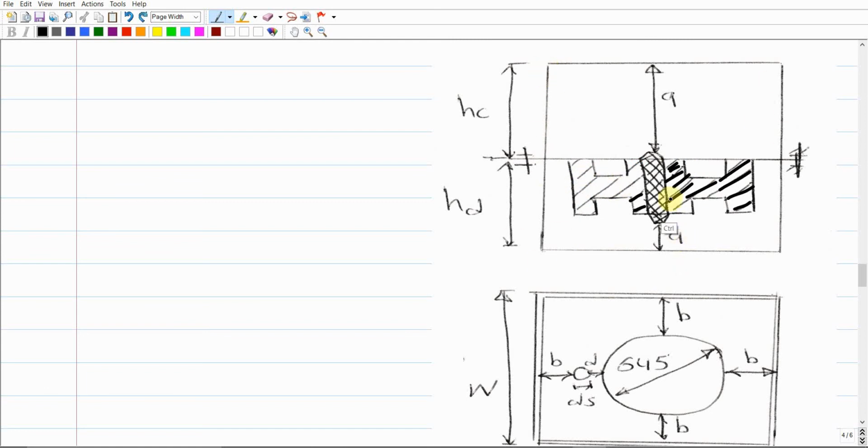as we agreed before, right? And as you can see, there is a standing vertically the core itself. This should be the thing in the middle, this should be the core, and these extra portions here are the core prints, right? And from our calculation, we find that this dimension is the H1 that we got from the table in the core design step by 70 millimeter, and the one on the top was the 0.6, the H1 that we got from the calculation before, right?